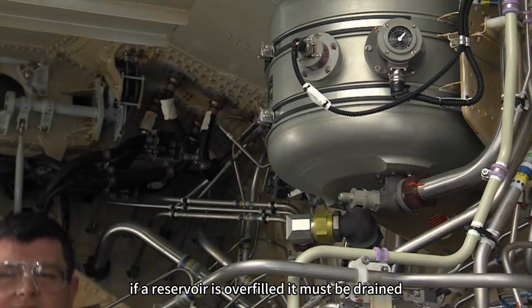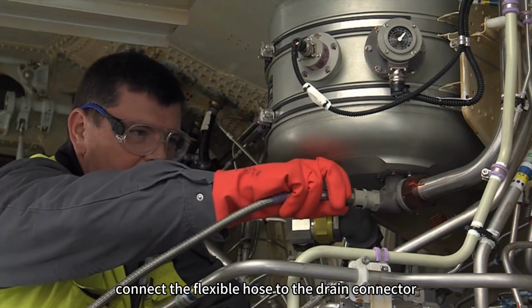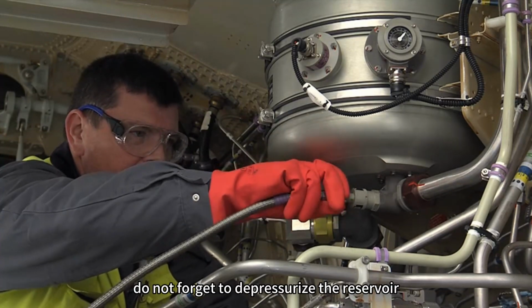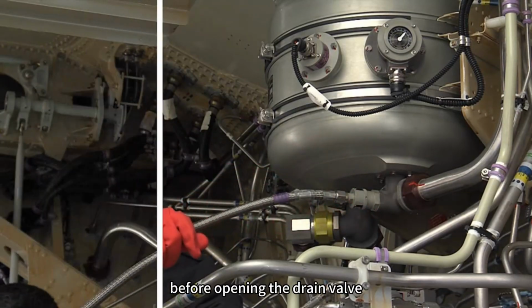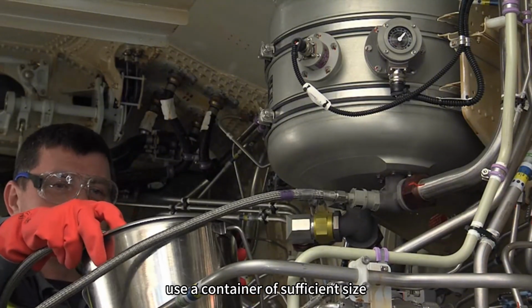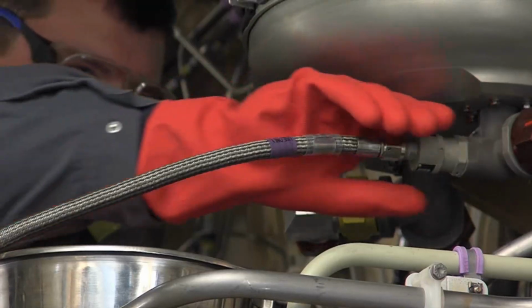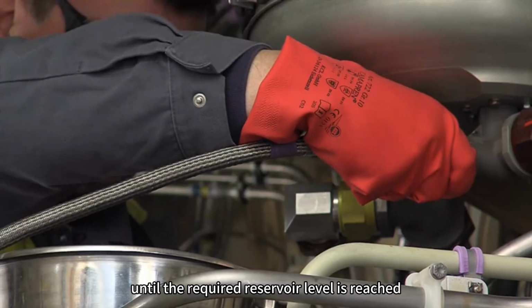If a reservoir is overfilled, it must be drained. Connect the flexible hose to the drain connector. Do not forget to depressurize the reservoir before opening the drain valve. Use a container of sufficient size to collect the excess fluid from the reservoir. Open the drain connector until the required reservoir level is reached.